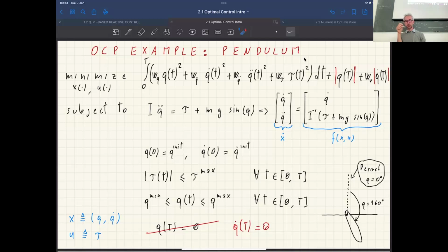So it's going to try to push the error really to 0 because it has a constant slope. So even when you're at a small error value, the gradient of that error is still going to be the same as it was when the error was huge.